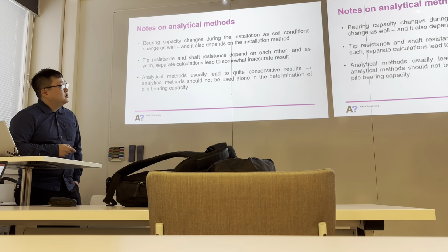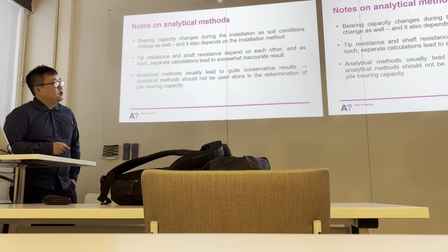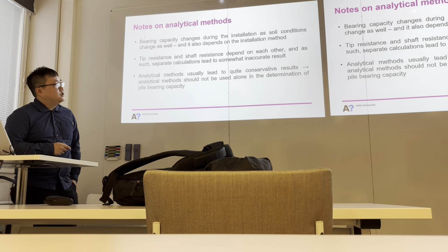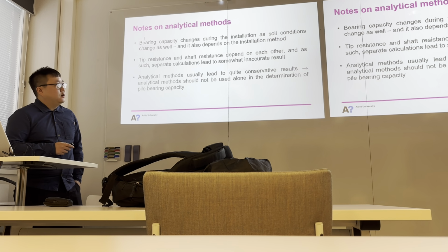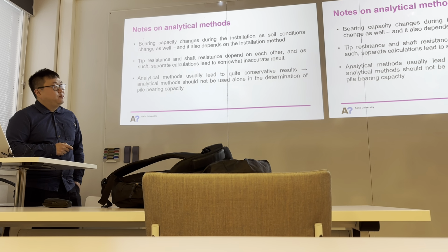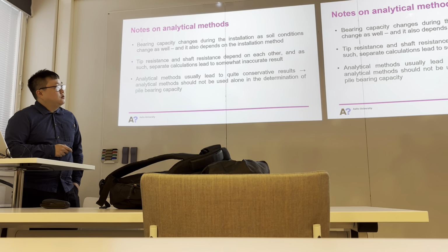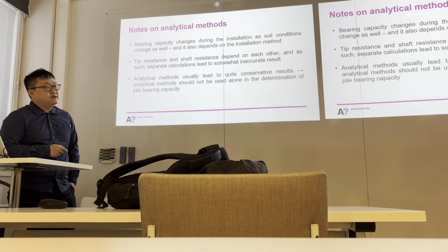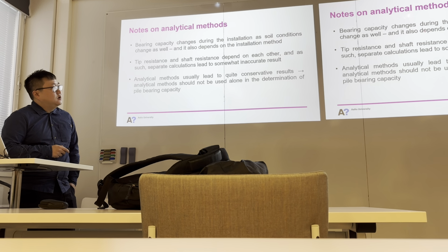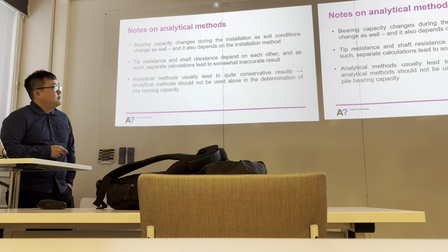So there are some notes on the analytical methods. The first one is that the bearing capacity changes during the installation as soil conditions change. We can imagine that if we push the pile into the soil, the soil will become denser during this process. So that's why the bearing capacity will change during this installation process. Also, this depends on different installation methods.